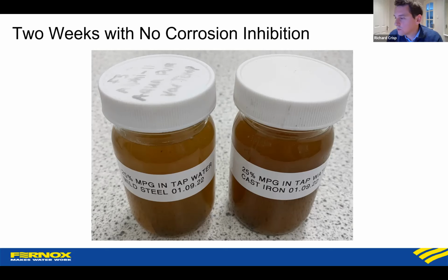So you could say, okay, well, is that realistic? You might be of the opinion that actually when you install it, you use deionized water, so it'll be less corrosive, which is a fair point. DI water seems to work very well initially because it has a low conductivity. But if that system isn't completely airtight, you'll get more and more air coming in, carbon dioxide, that will change and dissolve in the water.